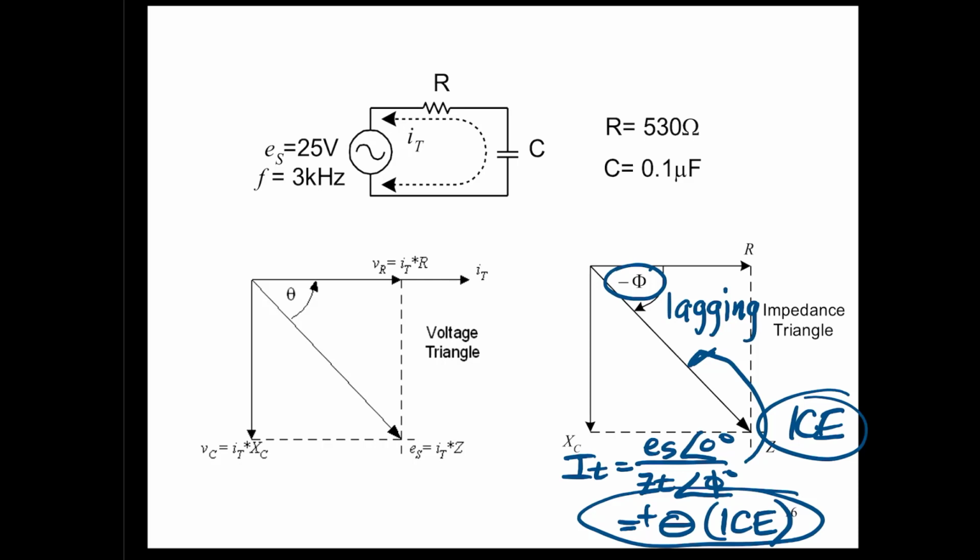And I can actually prove this with this voltage triangle that we see in this next diagram here. This is a voltage triangle. Notice how we have VR. We've got VC. It's not being shown directly as a triangle. It's showing the phasors coming from the same zero origin. But it's still an addition of the two values that can be shown as a triangle.